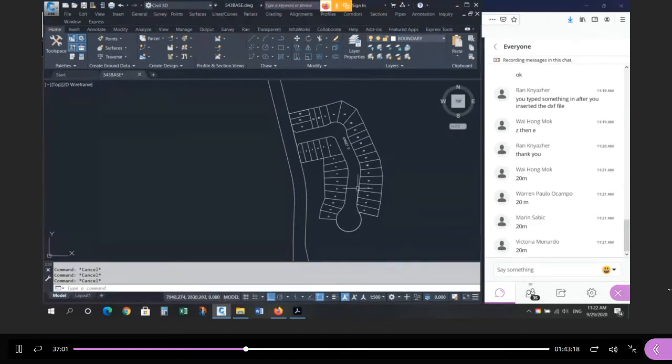Your standard width of 20 meters in Richmond Hill, and then you've got these kind of intersections, knuckles or crescents to deal with, and on occasion you might have a dead end to deal with. You can design these three items plus the standard width of road, then you've covered at least 90 to 95% of anything you're going to encounter when you're doing residential subdivisions. So it's a pretty good skill set that you can take with you.